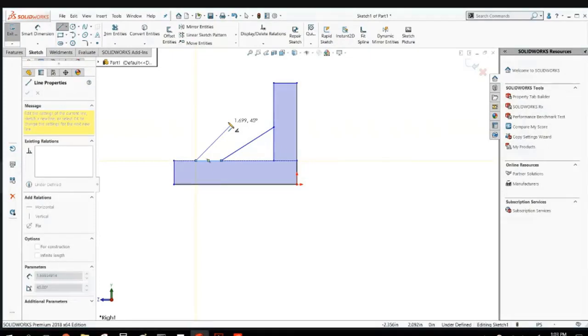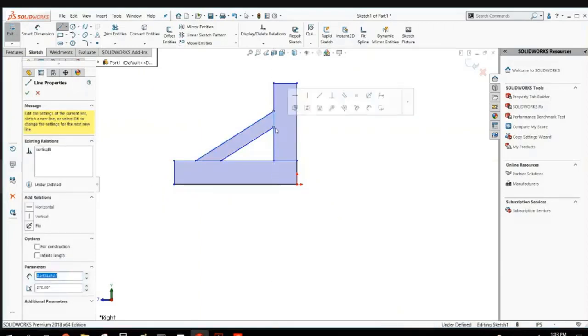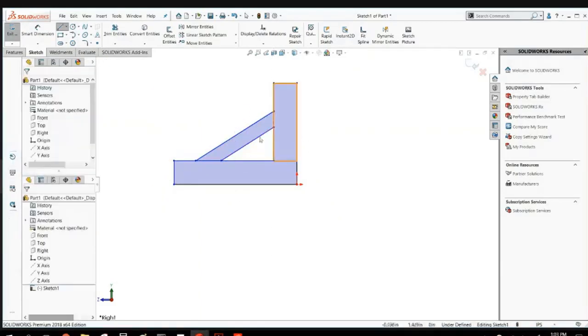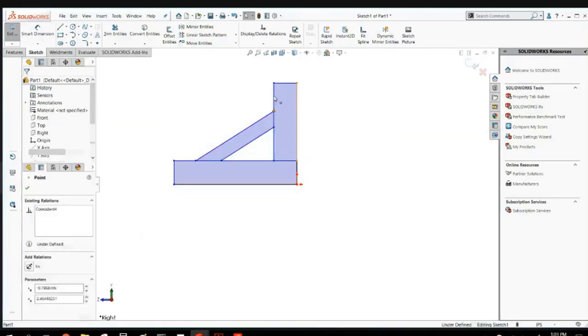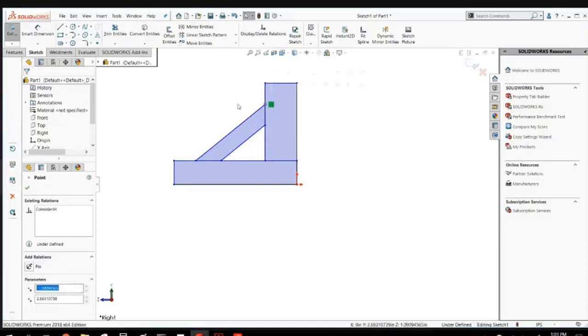If you're drawing a line and you want it to be referencing another line automatically, while you're drawing it, if you touch that line, you can see that now I can have this automatically be parallel to the line that I was starting with. Also in 2019, you'll see that once I've completely closed the gaps, then it fills in the area with shaded if I've got a closed contour.